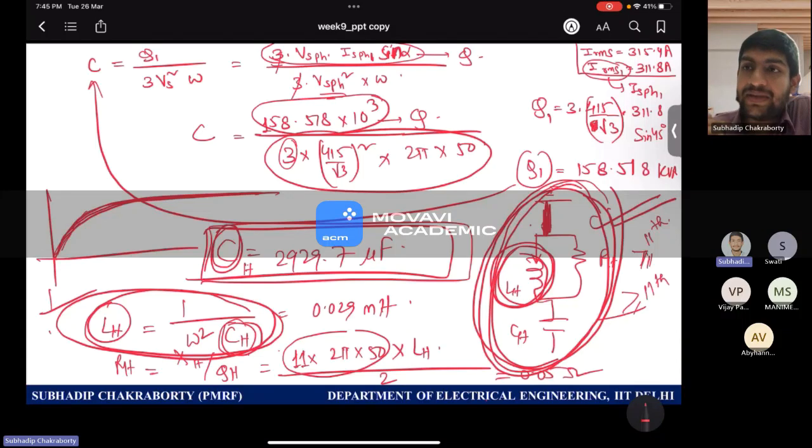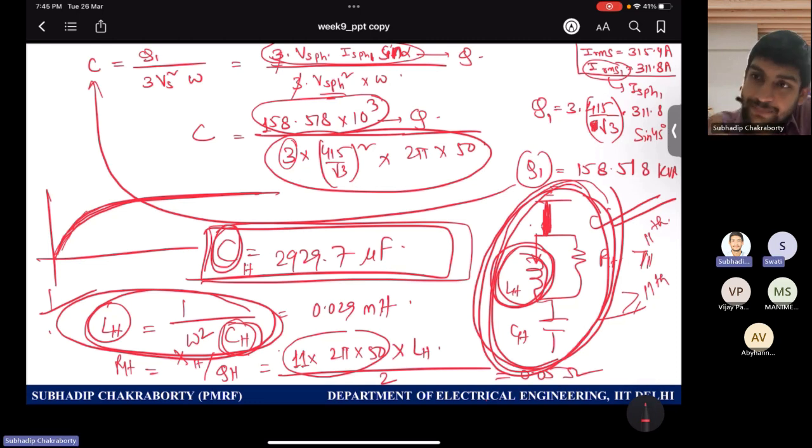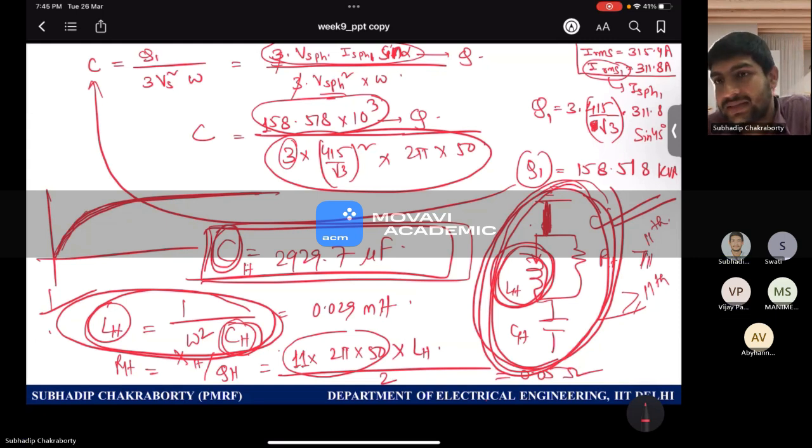Yes, impedance is low, but not too low. For single tuned, they are very low, because they are designed for that particular harmonic only. That resonance criteria will happen, limited by the R. So that is a trade-off that we need to make depending on the nature of the load connecting to the system.